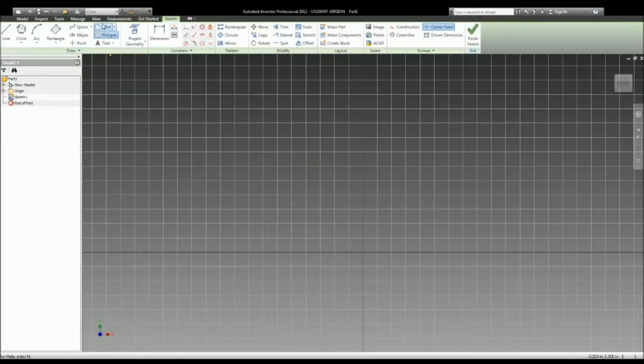Crud. I was going to use fillet with the polygon, so I'm just going to go ahead and draw something like that. Okay. So fillet. Fillet is a very fun tool. You have two options. You have fillet and you have chamfer. Fillet is for rounding off edges, and chamfer is just to remove an edge altogether. I'm going to start with fillet. When you have this little box, it asks for a value, and it's the radius of the circle that you want your corner to be filleted to. So I'm going to say 0.25 in this case.